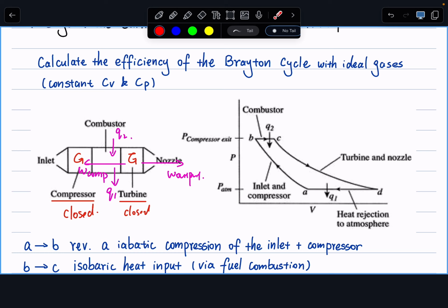And next up, now we have our Q2. What about our work? So for this process, how do we link work, heat, and something we know? We use our first law of thermodynamics. Remember, we have the system at rest, no external field, closed. So we are happy, we should be able to use our first law of thermodynamics. Delta U equals Q plus W. And do we know what is delta U for the cyclic process? That's 0.